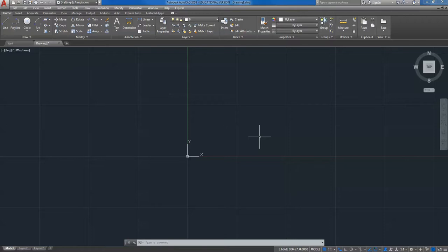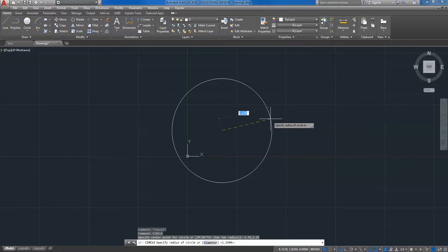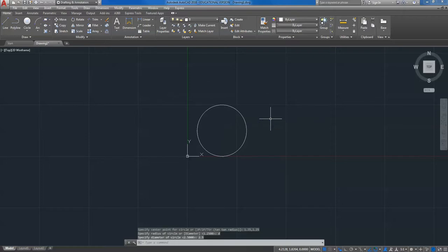All right, so really quickly, I'm just going to show you some of the basics for chapter 4. I'm going to go ahead and start creating circles. What you notice is you can do the command bar and type in circle, or if you look up to the very top to the left, you'll notice that the circle command is up there. The first problem, it's in the x direction is 1.75, comma, and 1.25 for the y, because that's half of 2.5. Now notice that the radius is called out. I can click on D for diameter, and I'm going to do 2.5 as the diameter.